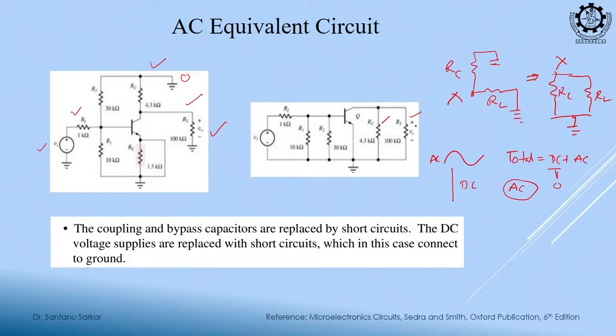Okay. So, what is the equivalent output load now? If I see this is output, what is the equivalent load? Previously it was only RL, right. Now it is RC parallel RL. So, suppose you find out the current IC, what is the drop here? And this drop has a minus sign, right. This is not sourcing, this is sinking actually. So, this is minus. So, this should be your V0, right. If I multiply by Vi and divide by Vi, then this will be my small signal gain.